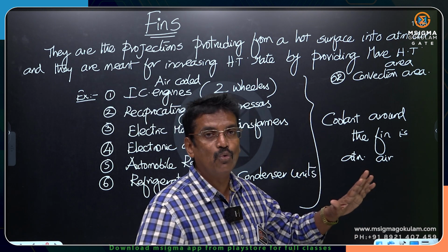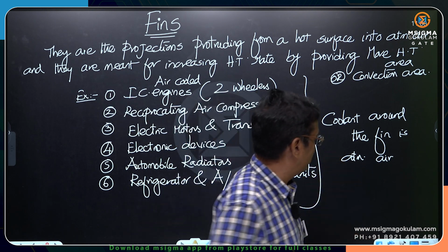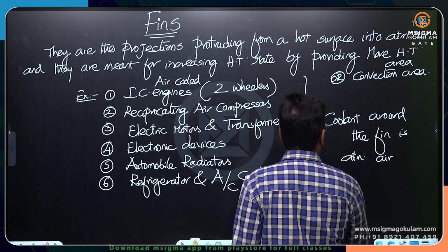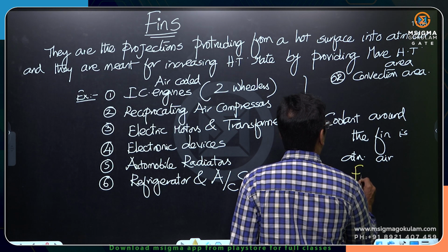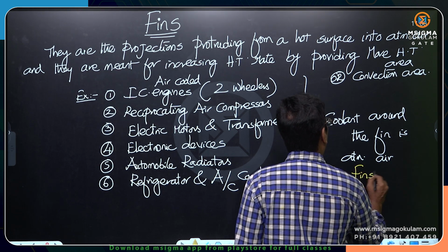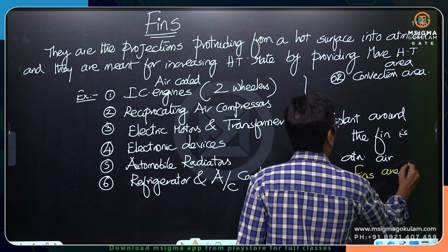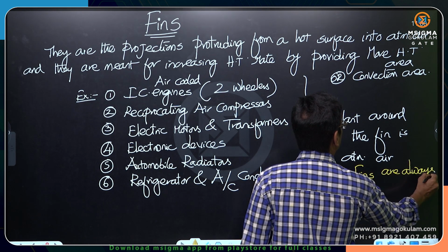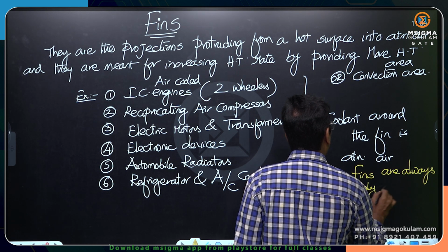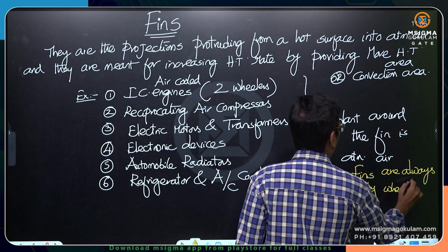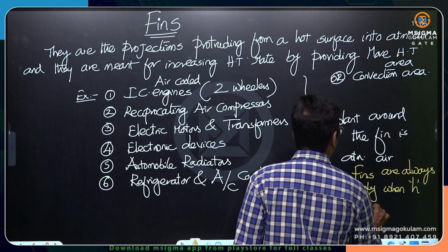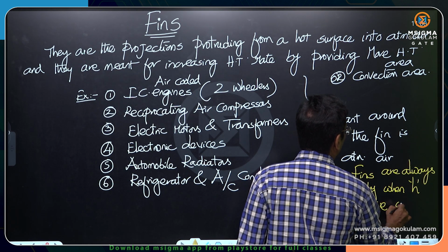Fins are always used only when the h is low. I am giving the important point here: fins are always used only when h is low, that is with gases.